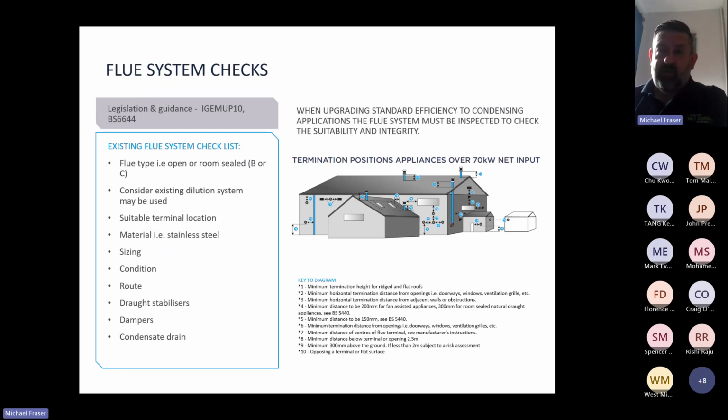Can be a very good way of getting your exhaust gases out if you can't take your flues to roof, but there's also a lot of things that need taken into consideration with the flue dilution system. For example, they plume like crazy on condensing appliances. Many a time the fire brigade have been called when it's just been a flue dilution system discharging on a cold day. But like I say, there can be a good get out if you can't get your flues to roof.